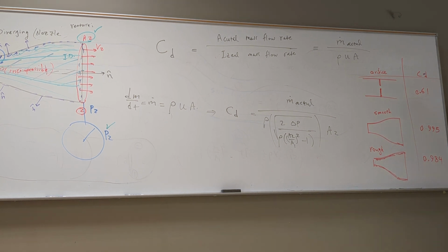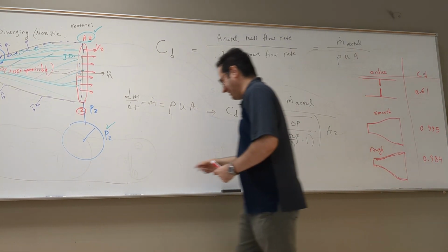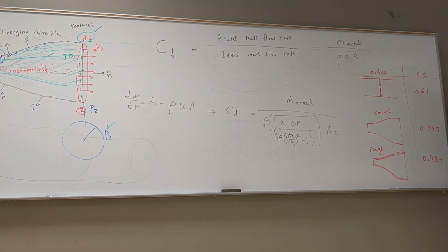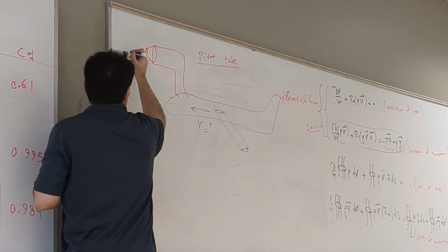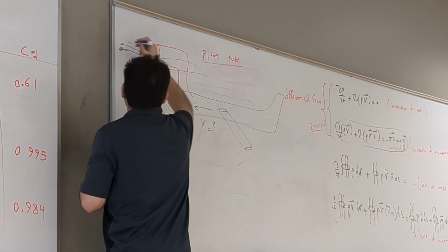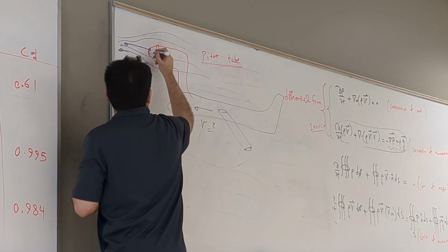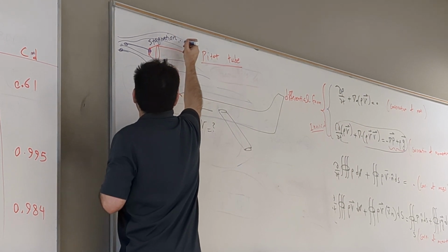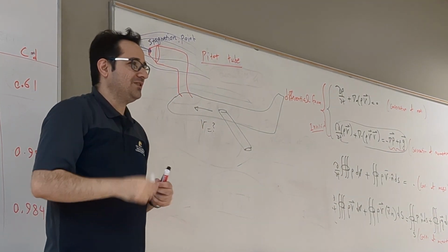It doesn't look very aerodynamic. So what happens in real life is, when this aircraft is moving, you get the air going around that, right? So you have a particle of air coming this way, going around it, another one going this way around it, another one going this way. But there is one particle that comes here, and we call it the stagnation point. So it's going to stay there with velocity 0.